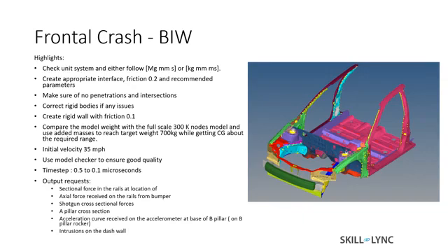With the given license limits on the student edition of HyperWorks, we have a 100k element limit on Radioss as well, and with that I have reduced a full vehicle model to subsystem models. Mainly for frontal crash, all the important parts from that car have been included. In frontal crash, the things we will be looking at are mainly a full frontal crash with all the sectional forces and some of the intrusions.